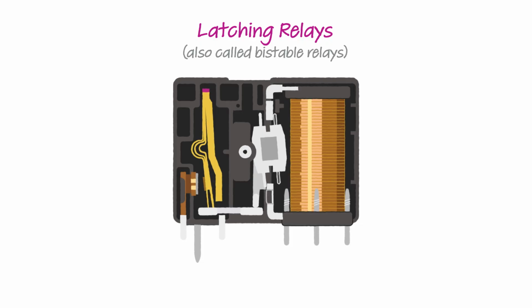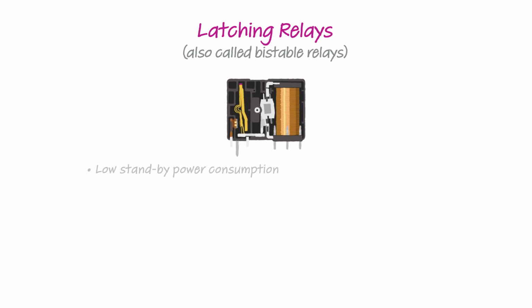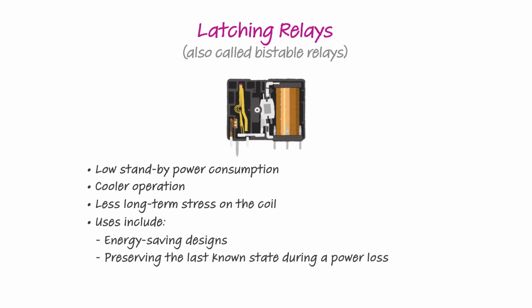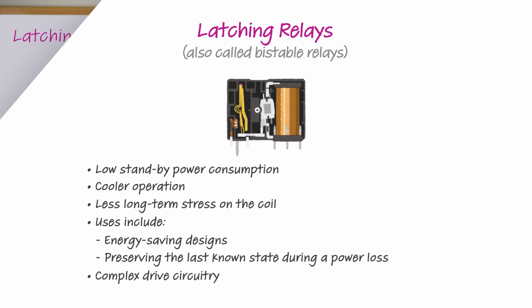Because the coil is not energized continuously, standby power is much lower. The relay runs cooler and the coil sees less long-term stress. This is helpful in energy-saving designs or applications where the last known state must be preserved during a power loss. The trade-off is that the drive circuitry is more complex.